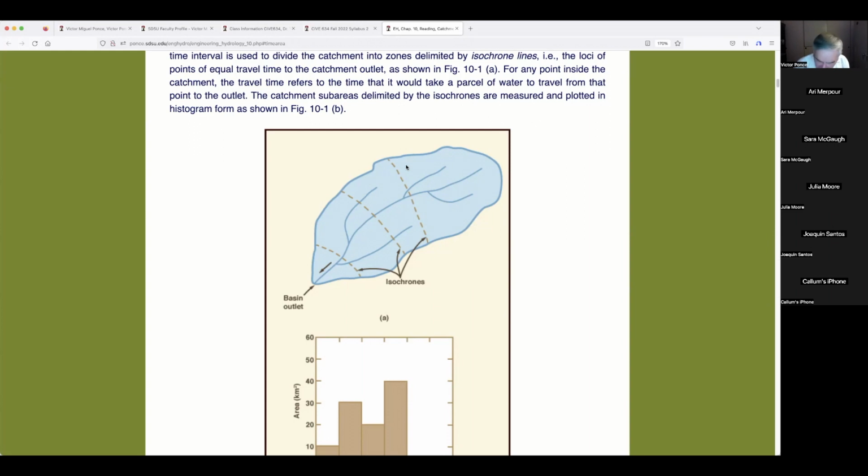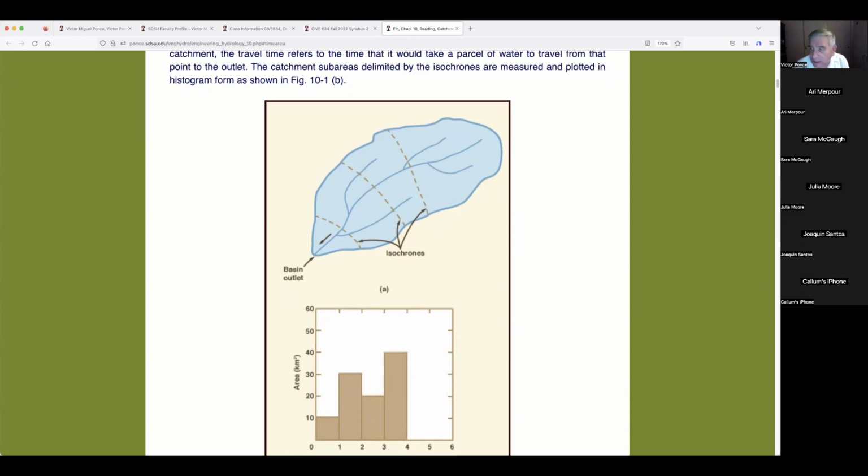And the reason why I'm bringing that up is because it relates to the issue of how easy or how difficult it is to calculate the time of concentration. Nevertheless, people do that all the time. It's bread and butter. You either use the Kirpich formula or the other formula. You can even go to the theoretical kinematic time of concentration. So there's several. Or the Papadakis-Kazan, it's a very good equation. I like it very much because, being of theoretical shape, it is based on data. So it's got both the strength of the theory and the data.